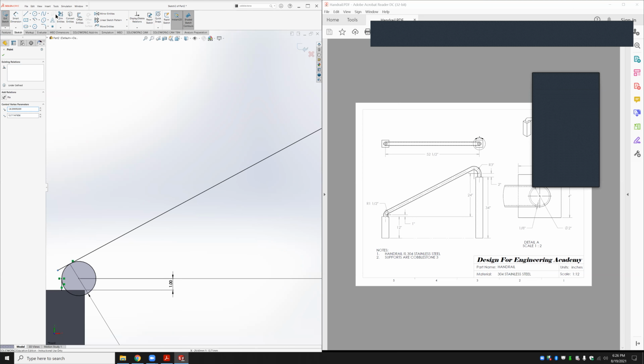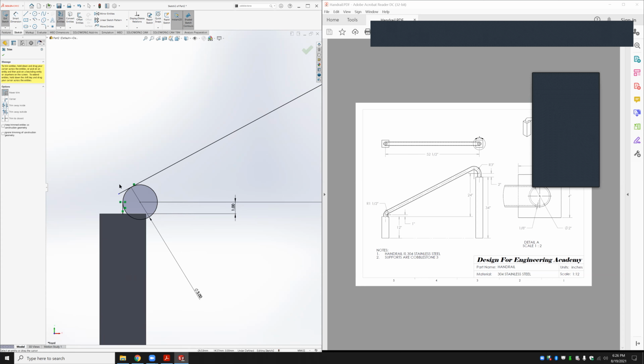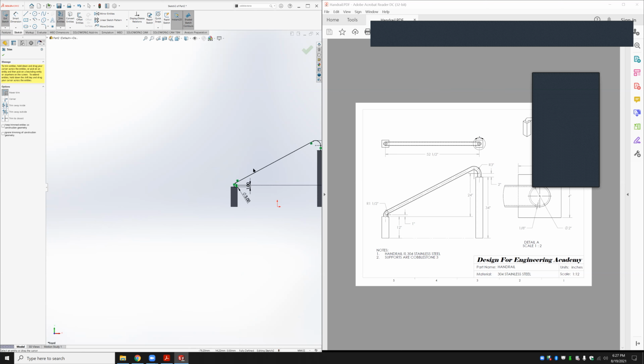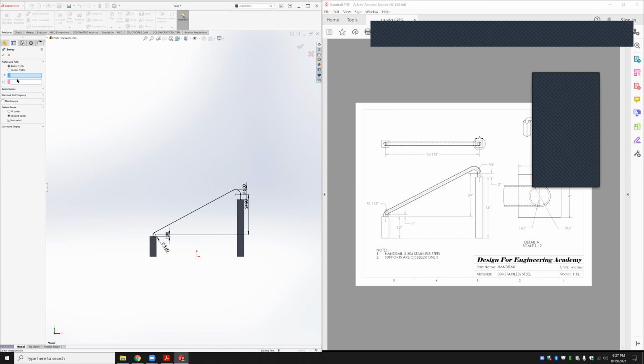But I don't care about that because I'm actually next going to trim that. Usually I personally never draw arcs. I'll use fillets, but not usually in here. I like circles and use trim from there. Probably circles are a better idea. Then I'll just go to sweep, and I want to do a circular profile with a thin feature.